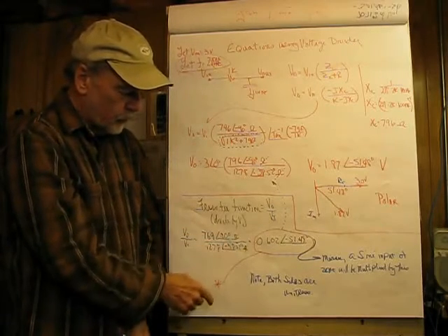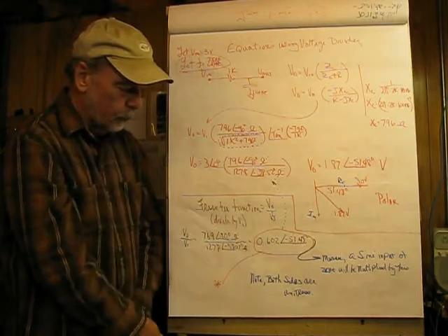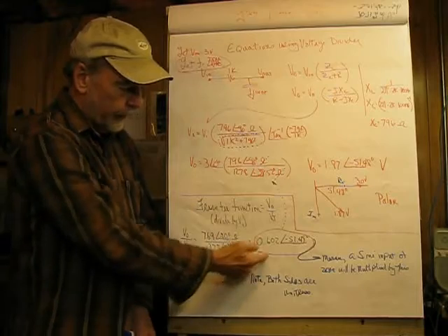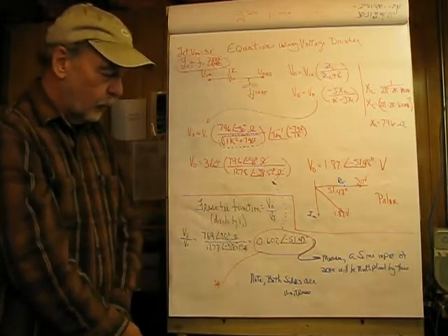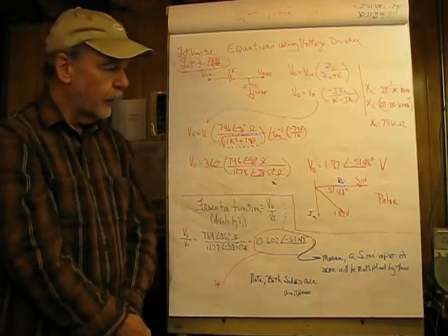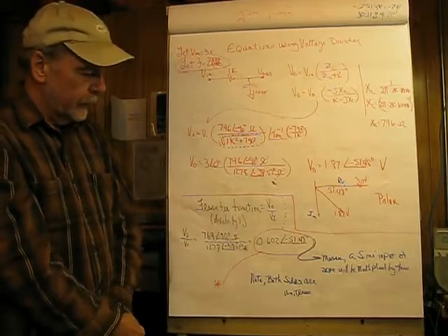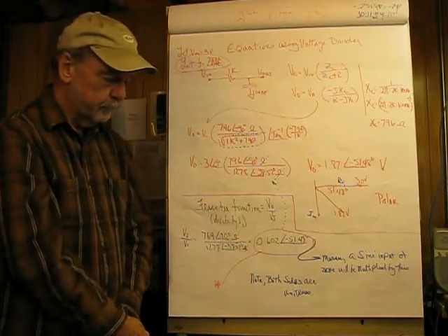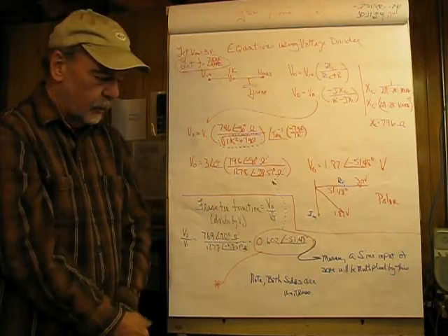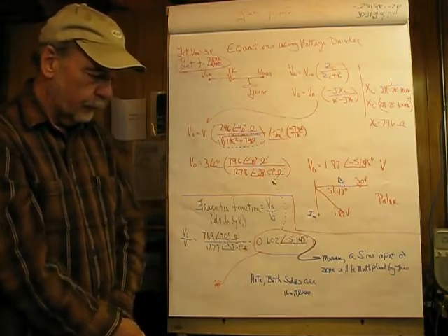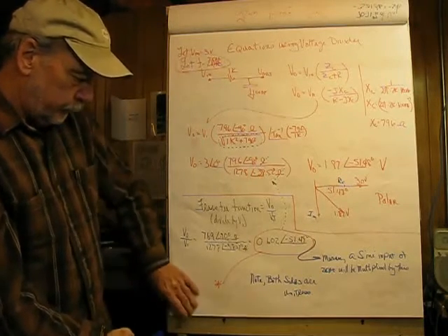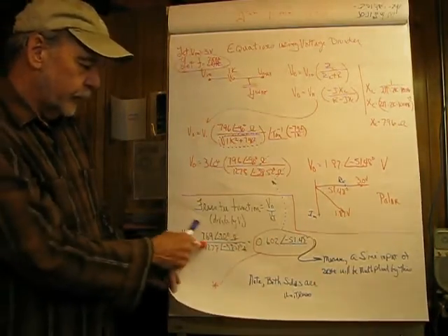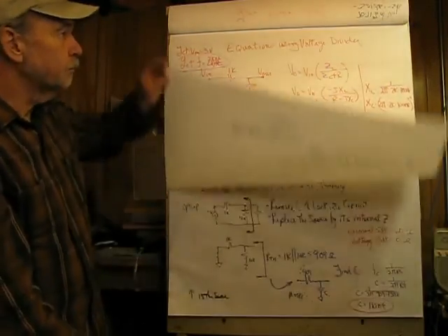This here is also dimensionless because we have ohms over ohms, and this just is the ratio of this guy over this guy at that angle. So that would be the transfer function of our network here. And the network, I don't have the schematic up, but it would simply be the resistor connected to the capacitor to ground. So that's not too bad. It's called a transfer function. And in our case, we would evaluate that again with 2 kilohertz. And again, both quantities are dimensionless.